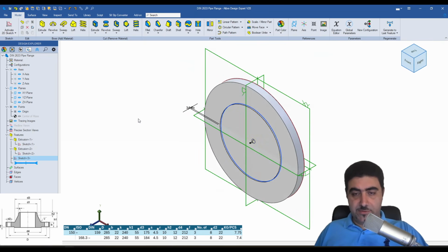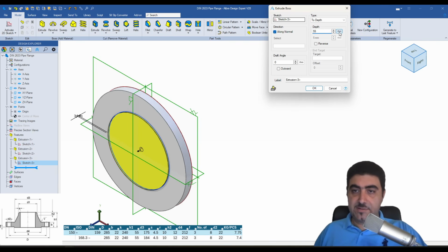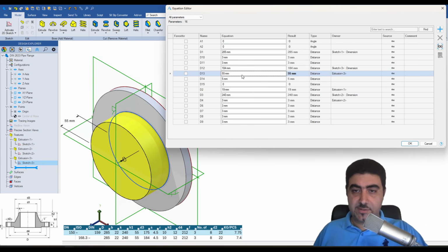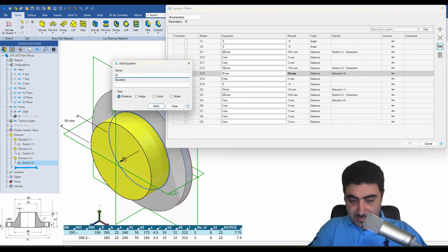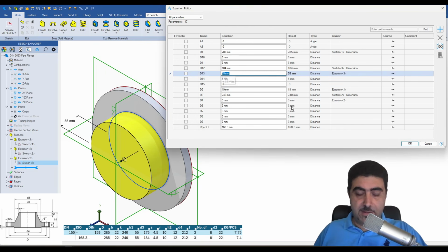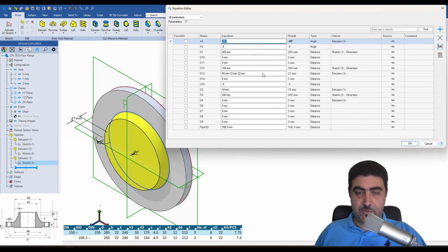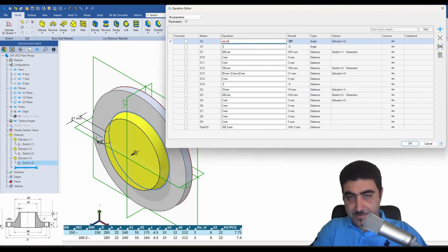And now I'm going to do the cone, and that started off from a 184. Right, and then I need to extrude it, and the overall is 55. Let's do it the same way we did in Fusion. So this is 55. Let me make a pipe OD value, which is this number. Anyway, so that's 55 minus 12 minus 22. Okay, now I have an angle here. Let's do 20 degrees inward. There we go. So here we're going to do A10, and we're going to say that this is D13.